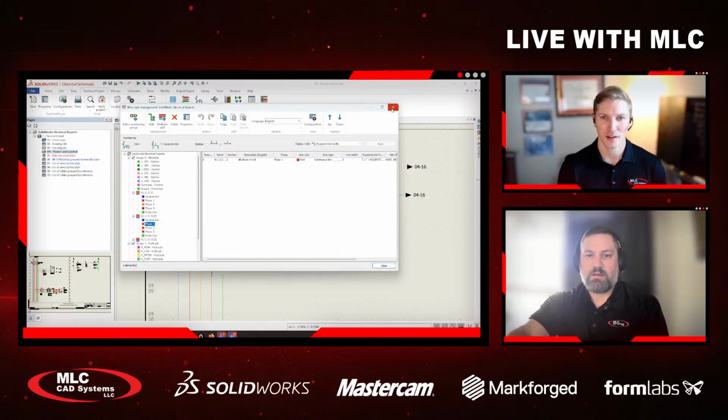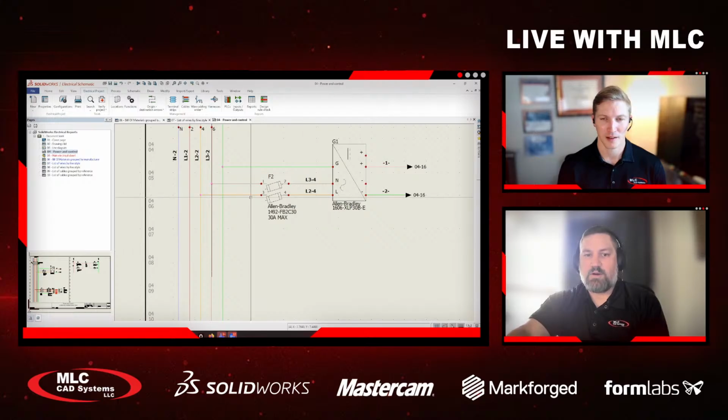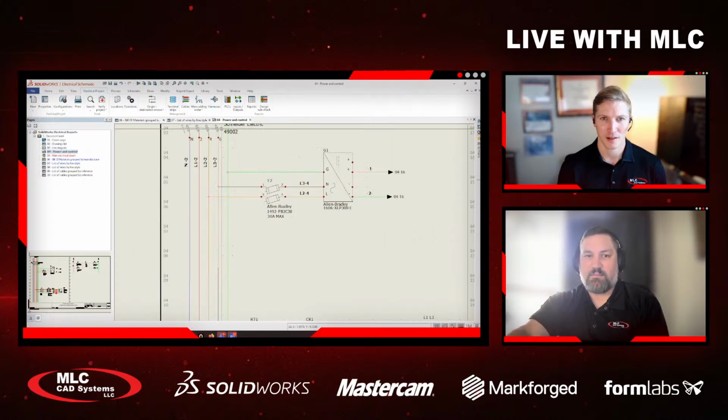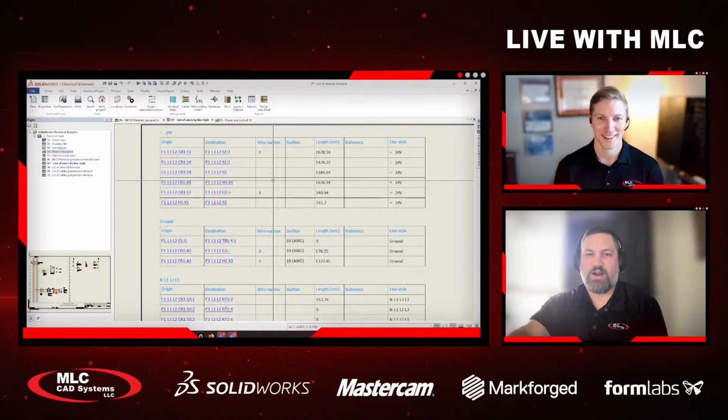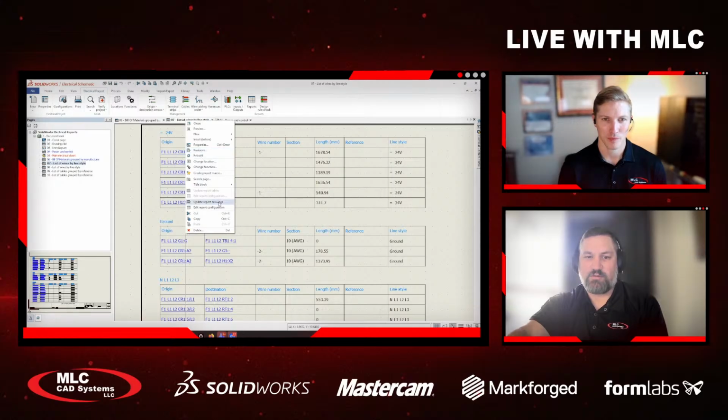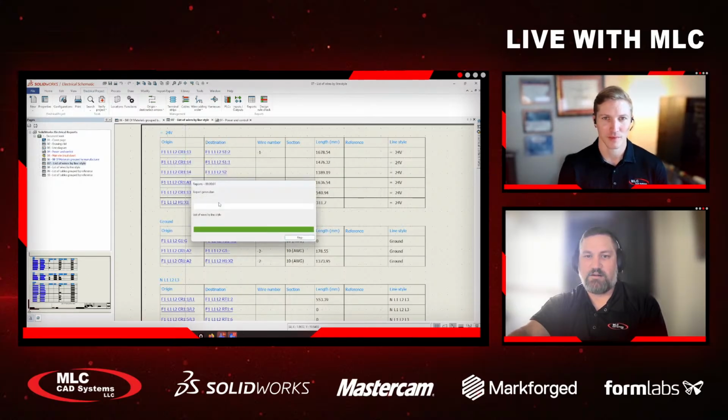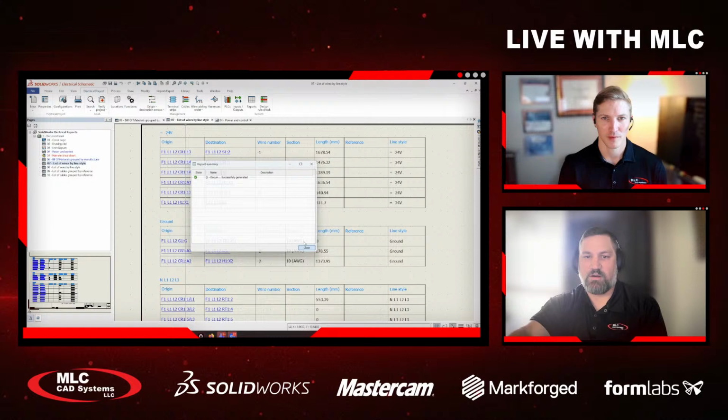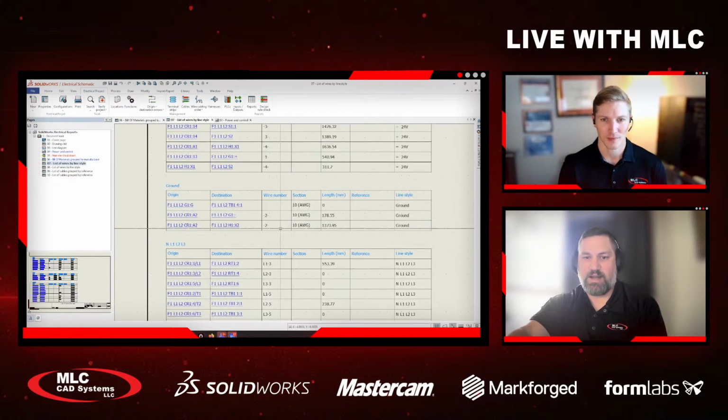Cool. And now what I want to do is add that, because you definitely caught me. You redlined this. We needed our wire numbers. So I'm going to right click on this and choose update report drawings again. And it's going to update all of our wire numbers into this report. And so now you'll see each one of them that needs a wire number has one.